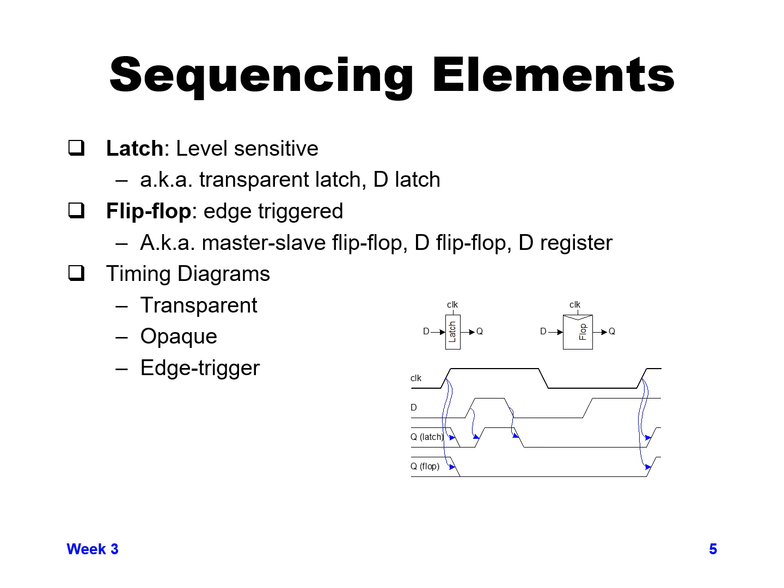At the time that clock is low, the latch is ignoring the value of D, so it stays low, and it continues to stay low until eventually the clock goes high again. Then when clock goes high, the latch becomes transparent and it follows the value of D at that point, and the flop samples the value of D at that instant, which is high, so the flop goes back high.